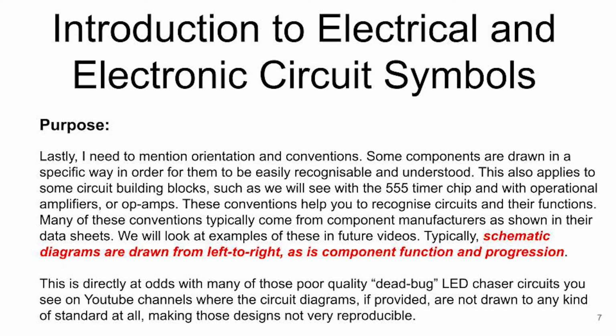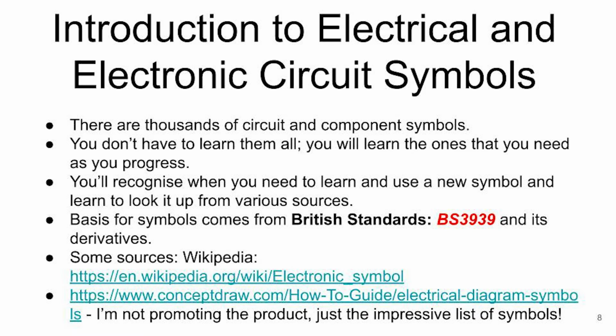Typically, schematic diagrams are drawn from left to right, as is component function and progression. This is directly at odds with many of those poor quality dead bug LED chaser circuits you see on YouTube channels, where the circuit diagrams, if provided, are not drawn to any kind of standard at all, making those designs not very reproducible. There are thousands of circuit and component symbols.